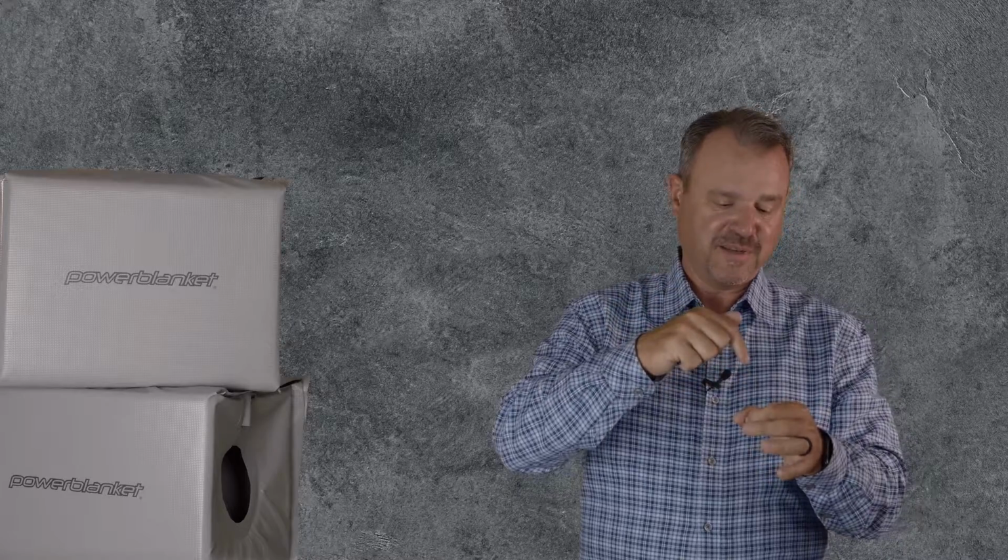Inside of a heating element is a product called magnesium oxide. It doesn't like water. And with about 6 inches of water sitting on top of those elements, it just absorbed all of them in there. So then when they went to turn the heaters on, they didn't work because they were all shorted out.